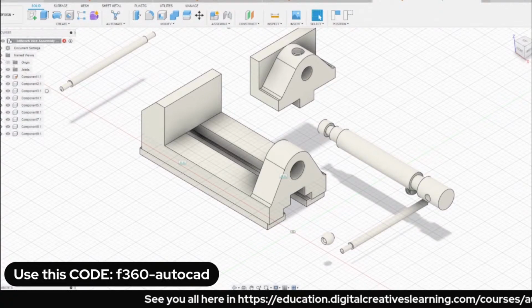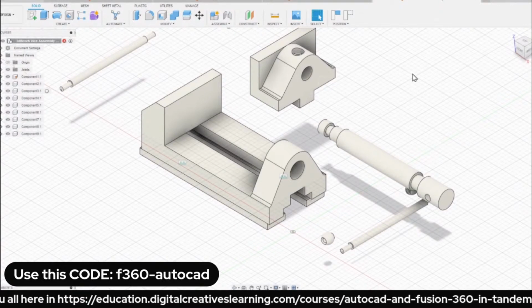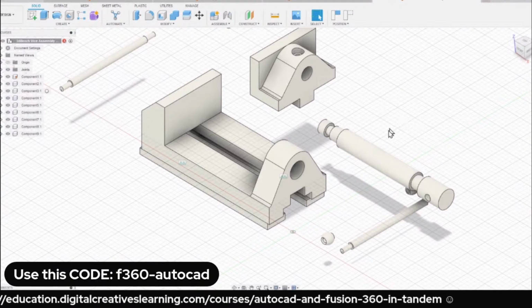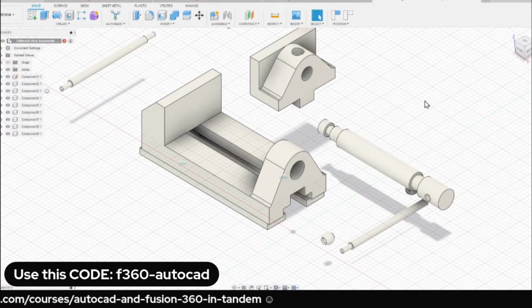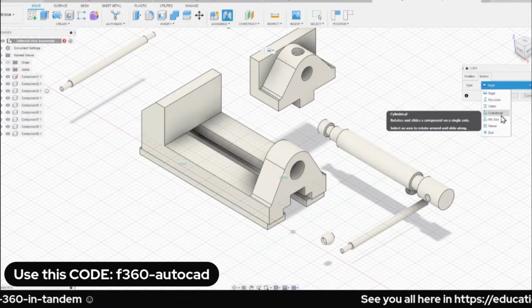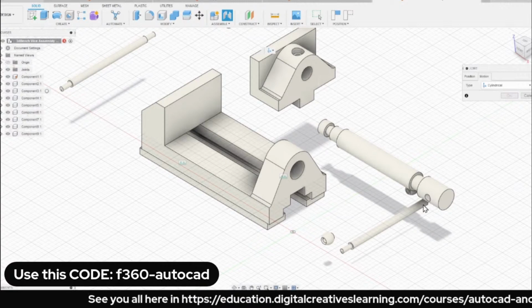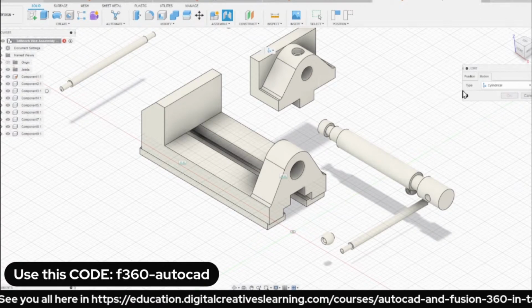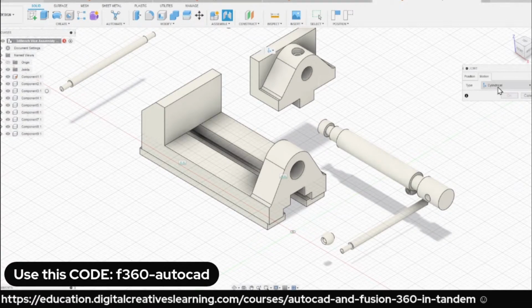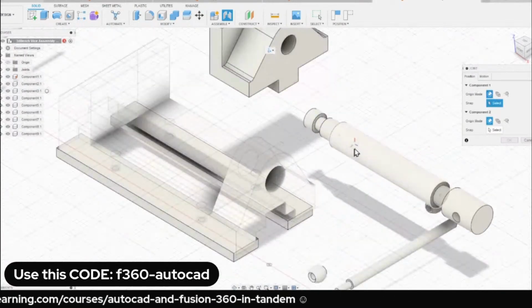So it will not only be having a revolute, but it will also have a linear action, right? With respect to x axis. So hitting J, the appropriate joint for that is actually cylindrical. It gives the opportunity to rotate, to revolve, and to move back and forth. So having the type as cylindrical, getting over to position.